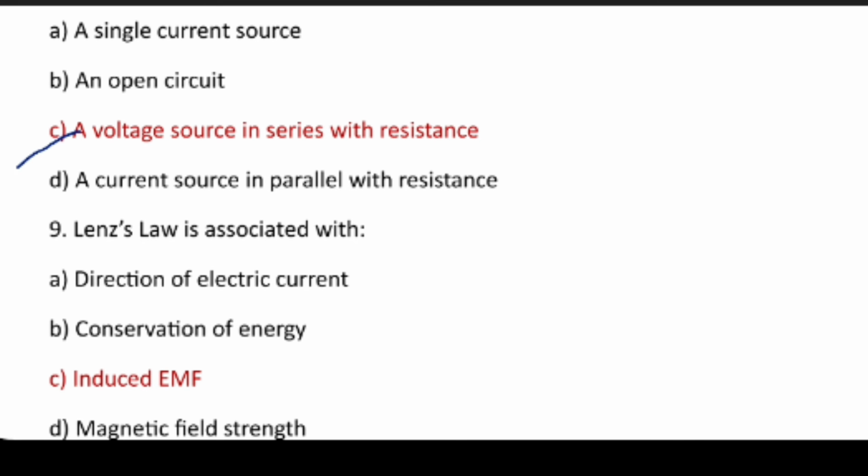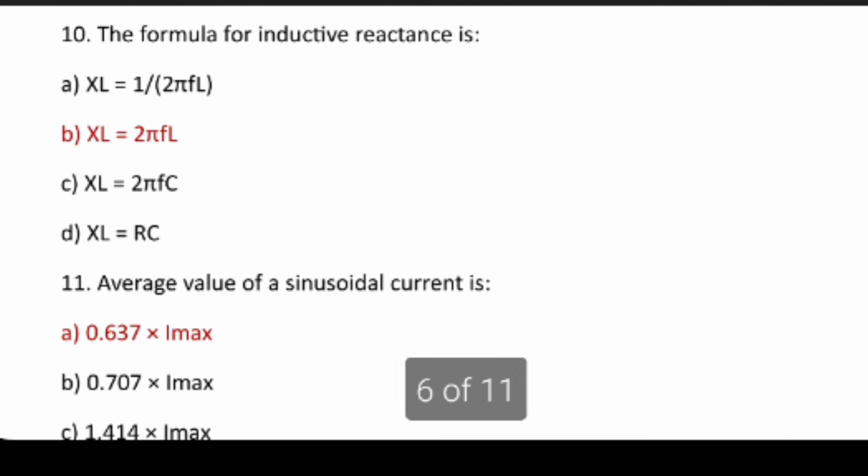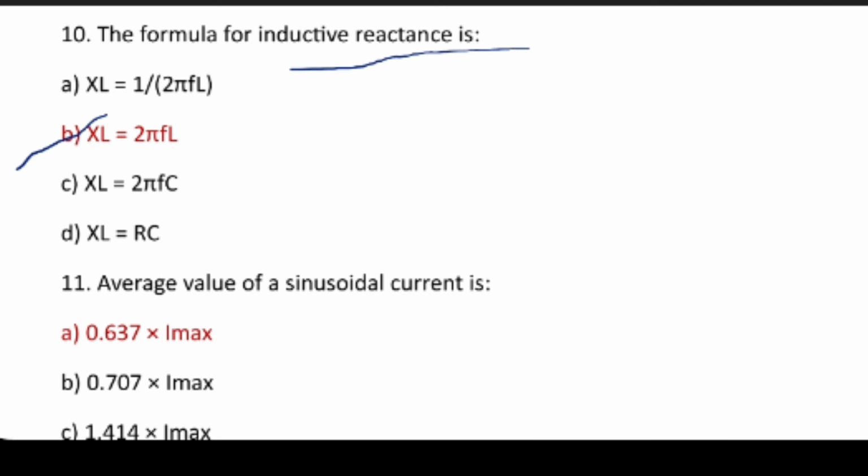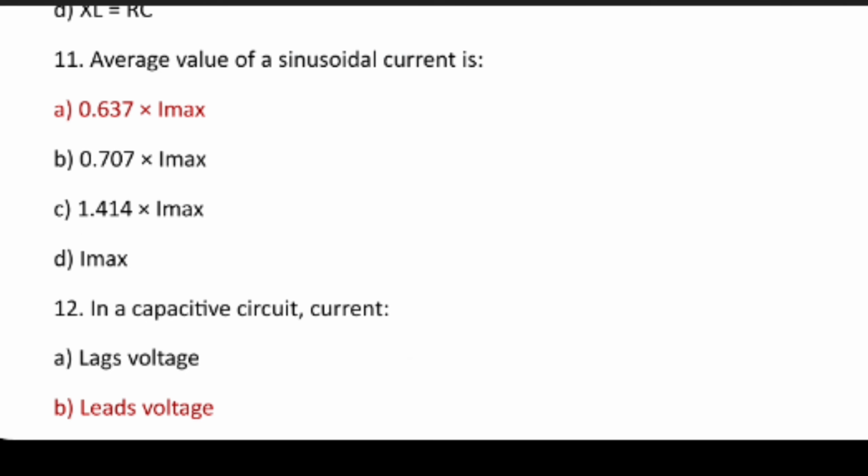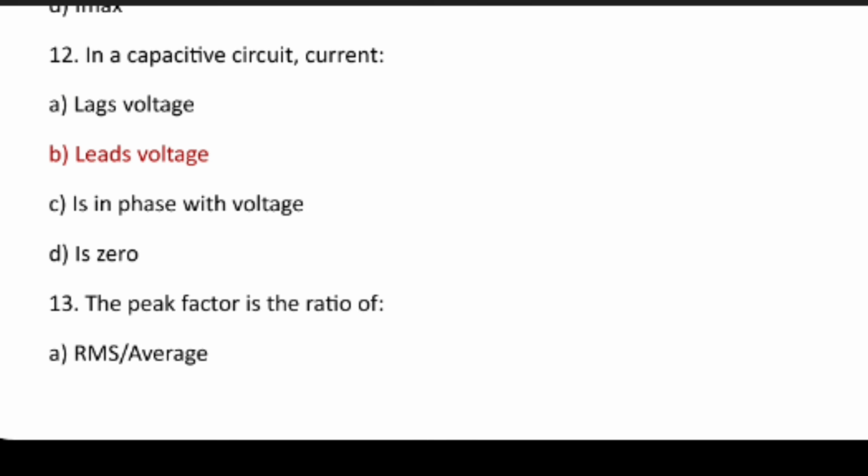Next, Lenz's law is associated with induced EMF. The formula for inductive reactance, option B, XL is equal to 2 pi FL. The average value of sinusoidal current is option A, 0.637 into I max. Next is the capacitive circuit, where the current leads the voltage.